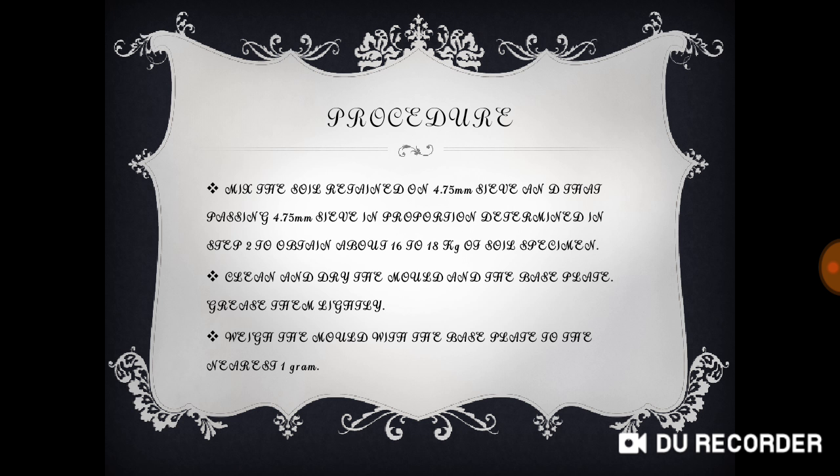For the fourth step, mix the soil retained on the 4.75 mm sieve and that passing the 4.75 mm sieve in the proportion determined in step 2 to obtain about 16 to 18 kilograms of soil specimen. On the fifth, clean and dry the mold and the base plate. Grease them lightly.